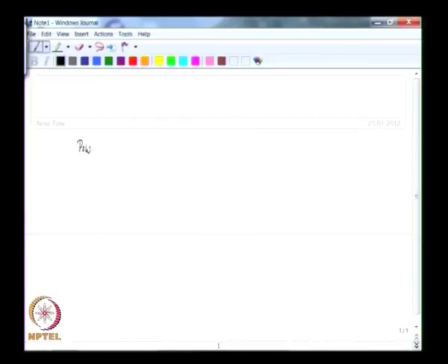the synchronous motor operation, the over excited and under excited modes of synchronous motor operation, and then from there we went on to look at the synchronous generator operation, where we said that if IQS is negative, it results in a synchronous generator mode. So these are the phasor diagrams, and then one more expression which is of importance in the synchronous machine analysis is the representation of power flow.